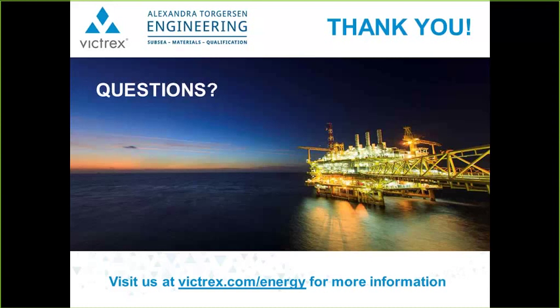Okay, great. On to the next question. Is an increase in crystallinity ever a problem in field applications? Oh, that's a very good question. So increasing crystallinity will increase the strength of a semi-crystalline material like PEEK. It will increase the strength, and it will increase the modulus of the material. And there may be a very small decrease in the elongation at break.